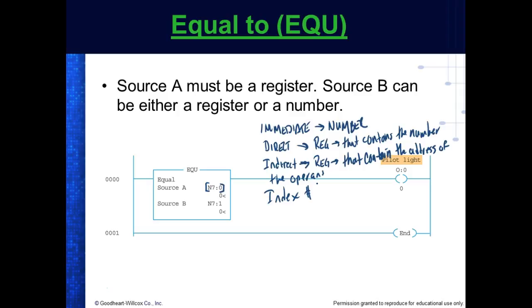What we would do is we would put tabs in the thing. We got a sequence up here that's really good, but it was motor driven. You had metal tabs on it, and every time you rotated, it would bring in a sequence of relays. And all you'd have to do is just change the tabs. You can change the sequence.